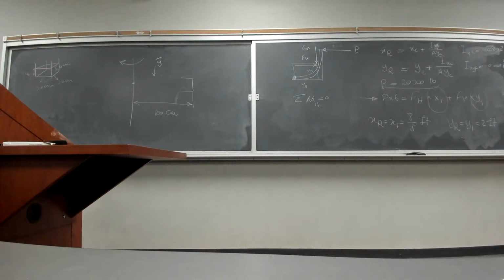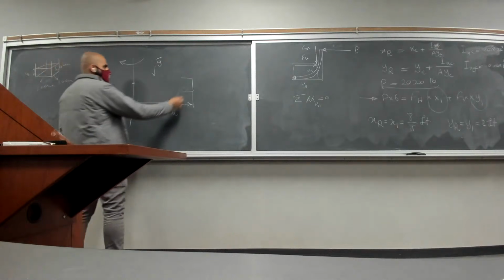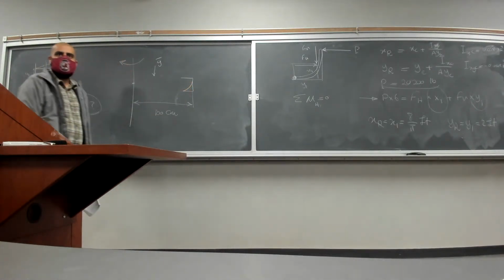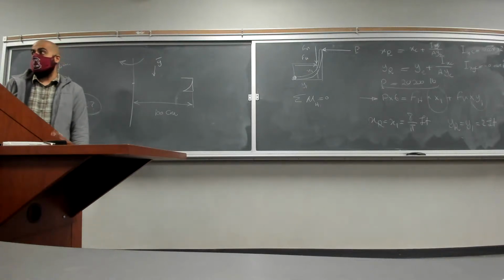We want to find the maximum rotational speed that the tank of water can be rotated with no water coming out of the tank. Is this clear? So you want to rotate this at a speed that essentially prevents any water coming out of the tank because of the gravitational force. If you start rotating it, it will be like this, right? This will be the water surface, the new water surface.